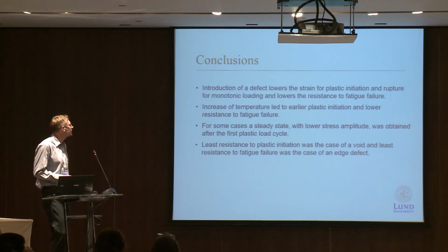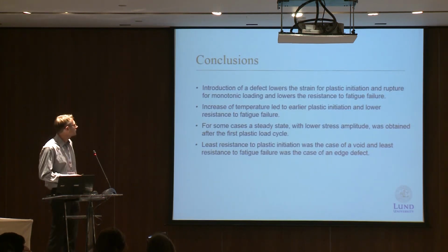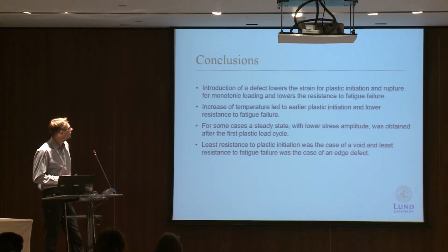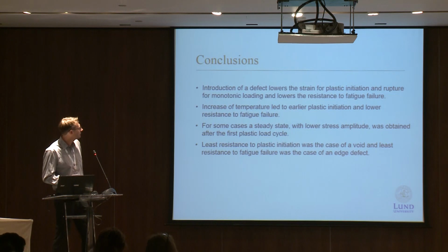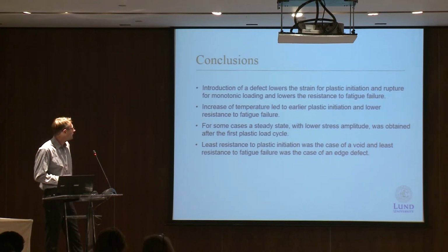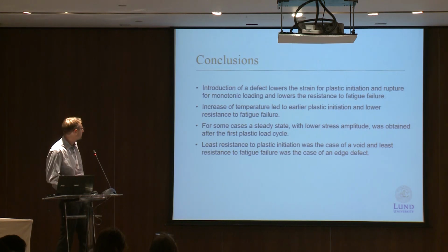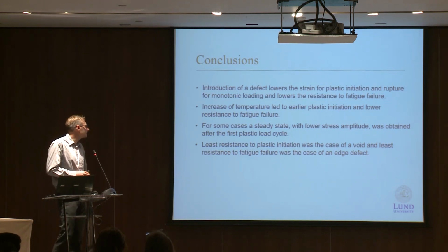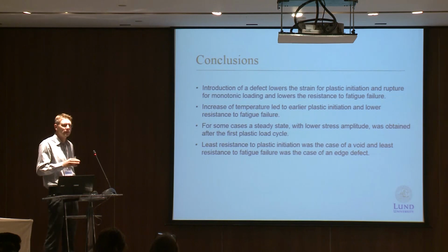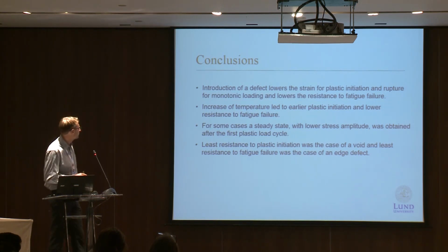So the conclusions of this work are that the introduction of a defect lowers the strain for plastic initiation and rupture for monotonic loading, and also lowers the resistance to fatigue failure. An increase in temperature led to earlier plastic initiation and lower resistance to fatigue failure. For some cases, we could reach some kind of steady state where nothing more happened in the material, but for some cases, this was never obtained.